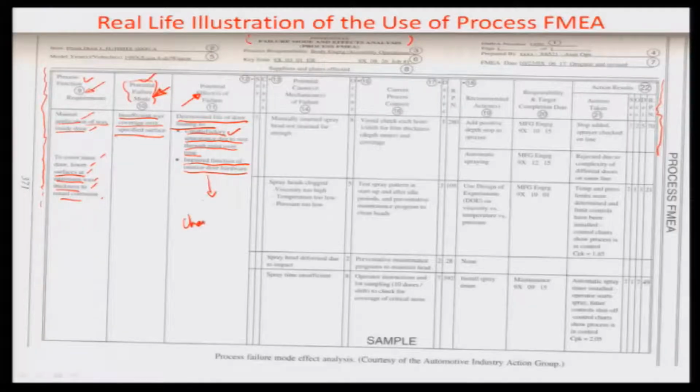For example, it may lead to the opening and closing of the trim boards again and again. It may lead to the mounting and taking out of things like regulators again and again, and it is not a very comfortable situation. So it is actually creating a chain of different problems, just because of the simple problem of the wax insufficiently covering the gap between the inside and the outside of the door in this particular situation.